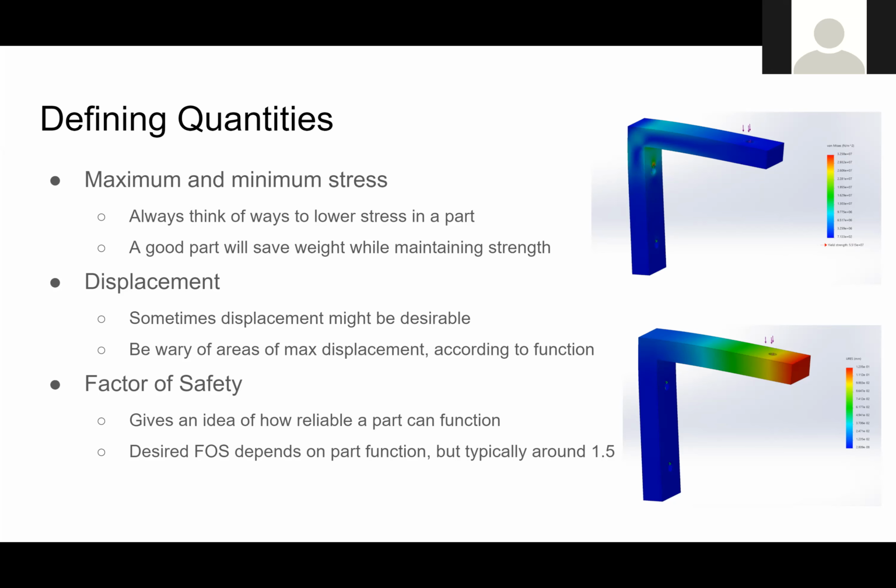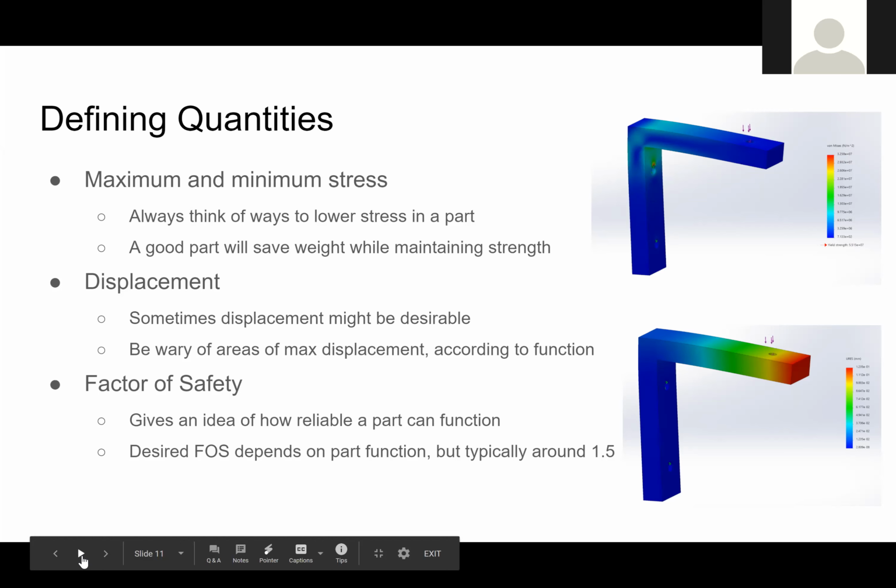You could also create a factor of safety plot. This will basically be analogous to your stress plot, but it'll show you the FOS, the factor of safety of your part. And it's good to see, oh, hey, my part will fail first here.